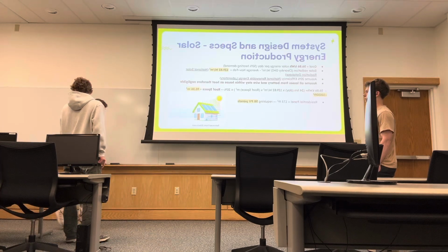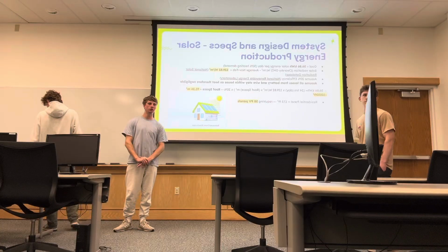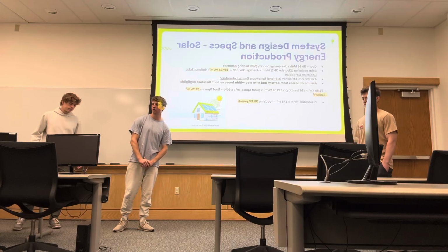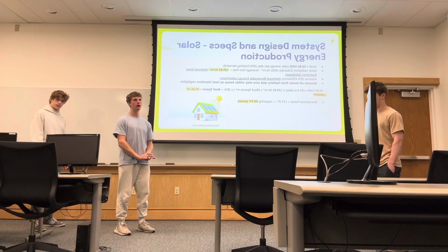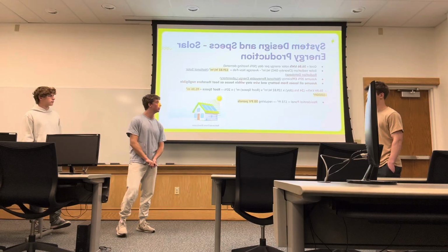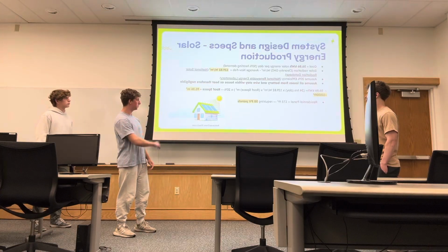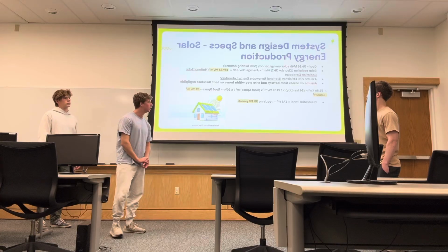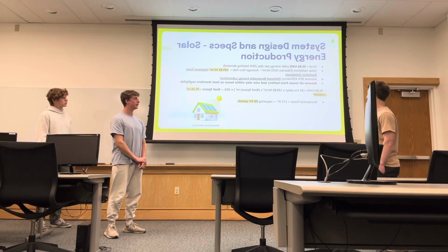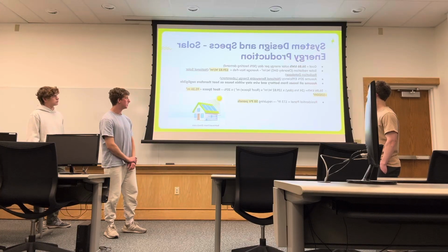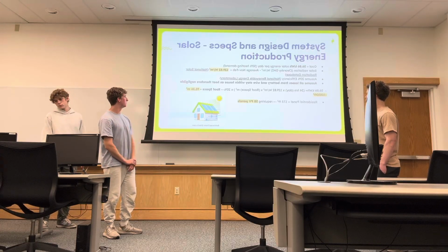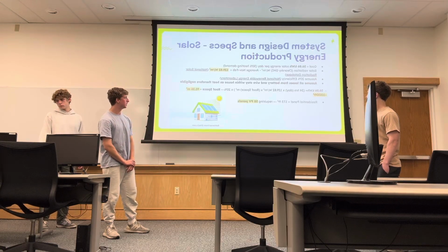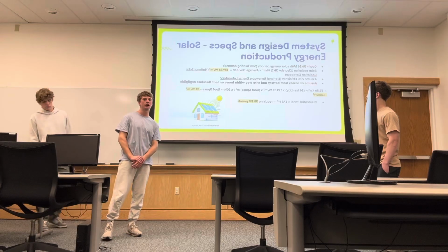All right, so since we found the total heating that we need to be 4.74 kilowatts, over a day that'd be about 113 kilowatt hours. So we determined for 50% efficiency, we wanted 56.8 kilowatt hours of solar energy every day, which is 50% of the heating demand.